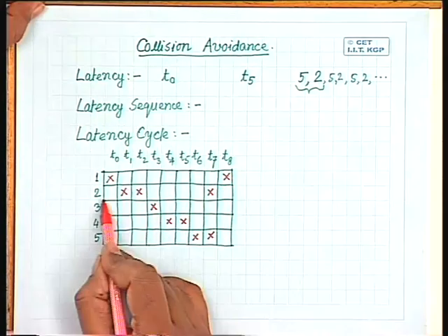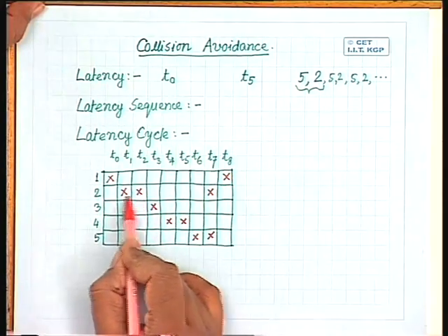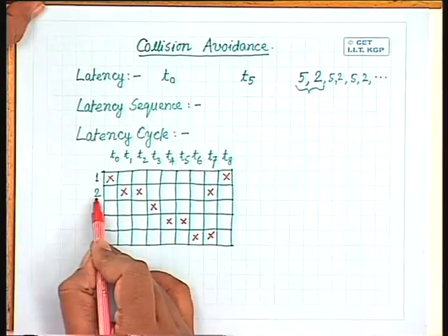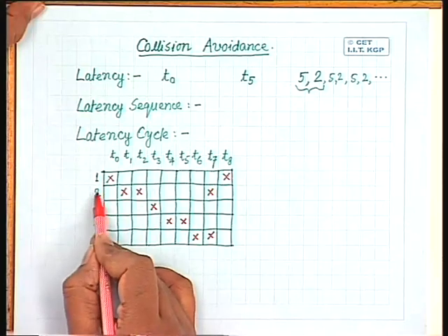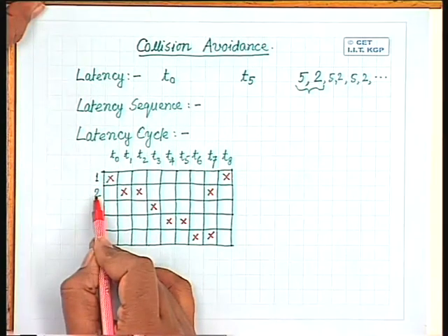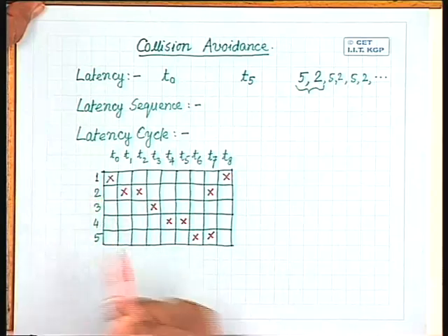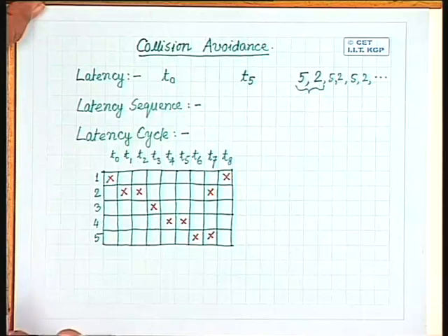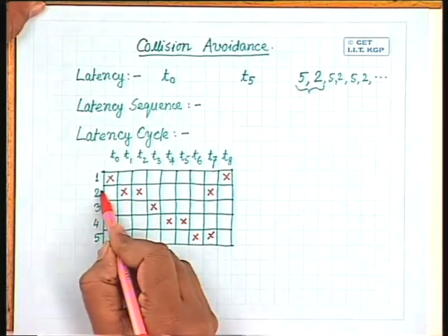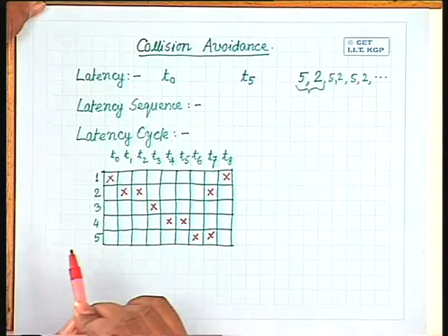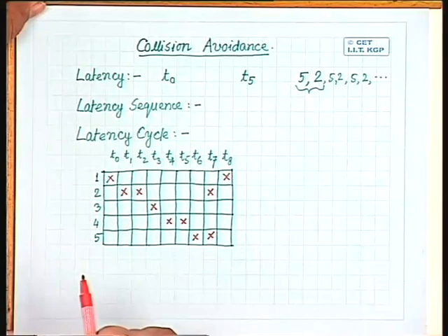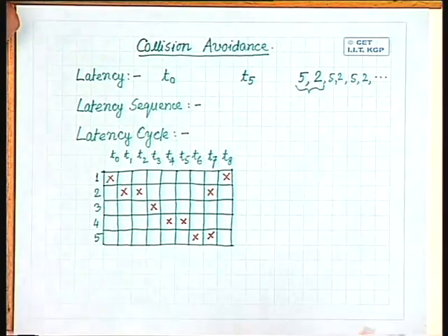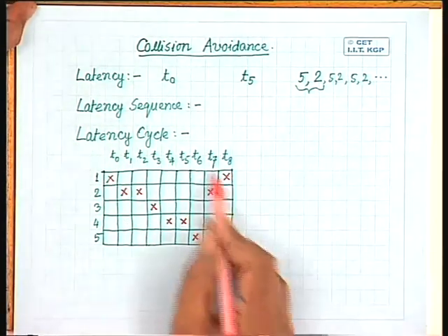Okay. Similarly, here for two consecutive time steps t1 and t2, the first task makes use of computation stage 2. Okay. So I should ensure that the second task that I initiate should never be initiated in such a way that use of this computation stage 2 is simultaneous for both task 1 and task 2. Okay. So I have to identify what are the time steps when I can initiate the second and subsequent tasks by analyzing this reservation table.